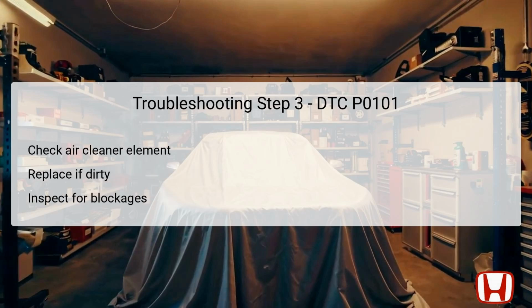Step 3 involves checking the air cleaner element for dirt and blockages that could restrict airflow to the engine. A dirty air cleaner will significantly impact the MAF sensor's ability to function effectively, leading to inaccurate airflow measurements.